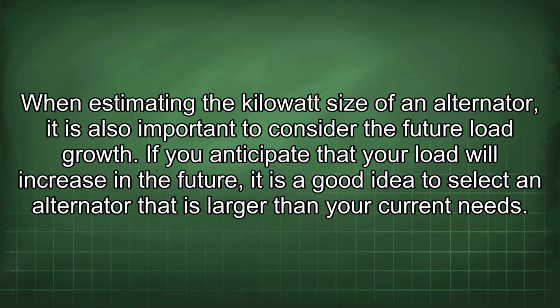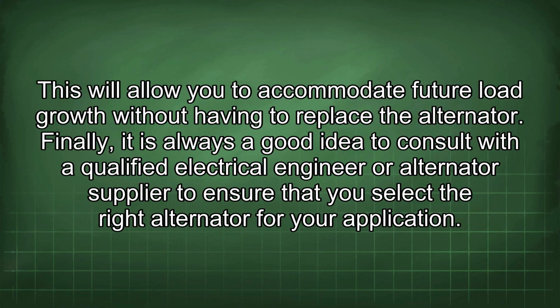When estimating the kilowatt size of an alternator, it is also important to consider the future load growth. If you anticipate that your load will increase in the future, it is a good idea to select an alternator that is larger than your current needs. This will allow you to accommodate future load growth without having to replace the alternator.